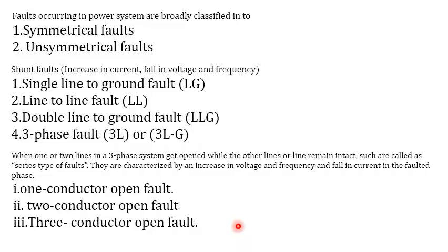So the fault current is the same in all three phases, and hence the system remains balanced after the fault occurs. Knowing the voltage and current in one phase is sufficient to determine them in the other two phases, because it is symmetrical in nature. In the case of the unsymmetrical fault, what will happen? The fault current will not remain the same, so the system is rendered unbalanced.